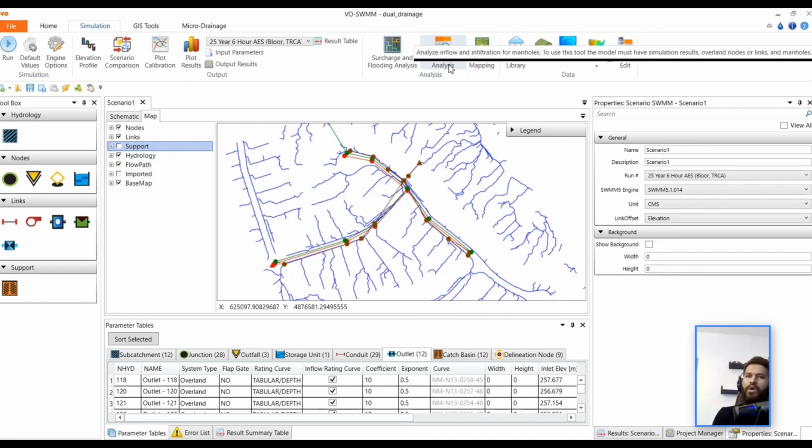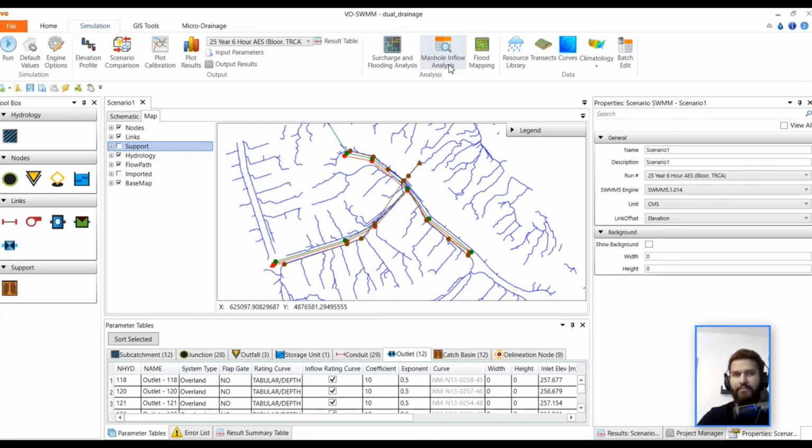We technically can't do the infiltration analysis because for infiltration analysis, we technically need to do flow monitoring. There are so many different ways to do flow monitoring. Also, Smart City Water does provide flow monitoring, and Data Current is the module to do so. But because we have no idea what exactly is going on down there in the laterals or in the sanitary pipes, we need some machines or some system to go through the sanitary pipes to check if there is any infiltration. So technically what we're doing is the manhole inflow analysis, which is what we're seeing through the manhole lids.